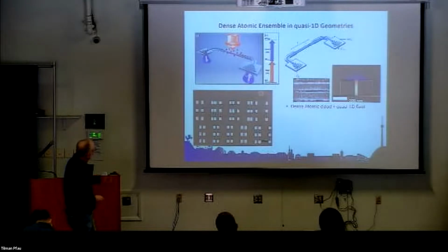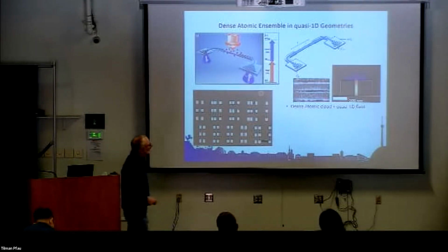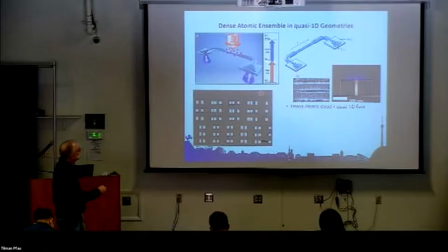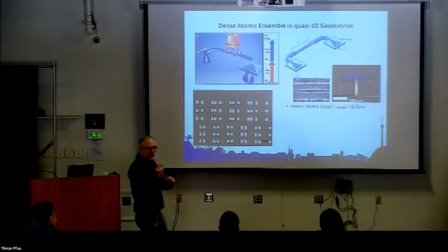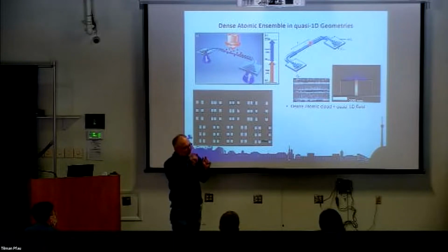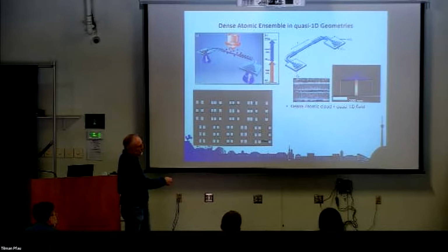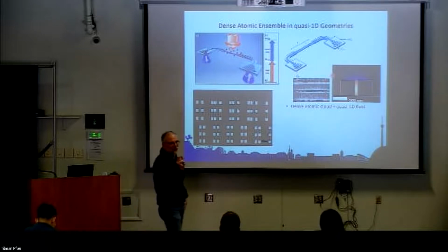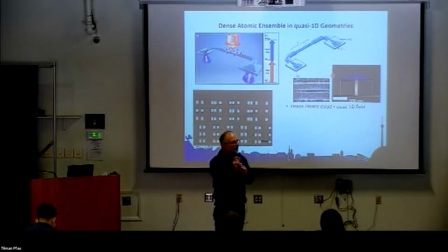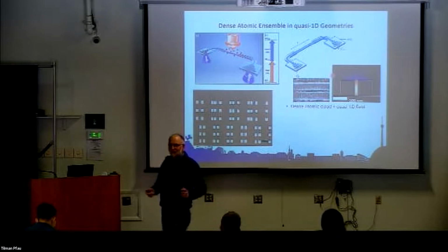So just to show you this first. This is the structure where we do the experiment. We couple in with our grating coupler and couple out on the other side. And then in the middle, there's an open region. But this time, it's not just a single waveguide. It is a waveguide that has a little cut in the center. So here is an electron microscopy picture of that structure. This gap here is about 50 nanometers only. Much smaller than the wavelength. So transversally, clearly, it's in the near field. Everything is in the near field.